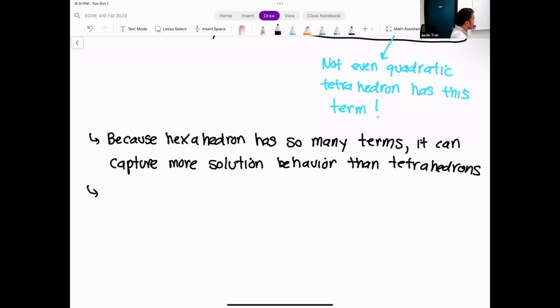All right. So in general, if you can put a hexahedral mesh on your finite element model, you're going to produce a better quality solution, more than likely. Of course, the downside is that it's not always possible or not always easy to produce a hexahedral mesh on a geometry.